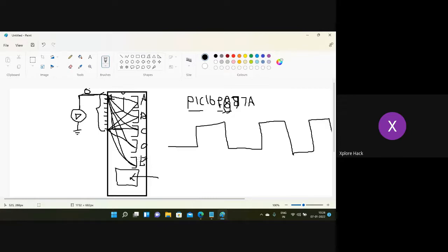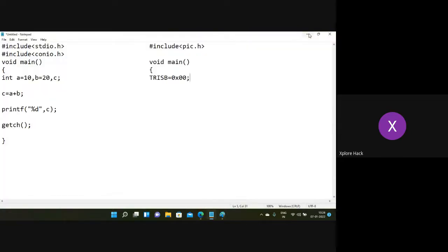This microcontroller can take 8 pins in each port, and if you are configuring the pins as output, then you have to give 0 in this place. After this, we cannot add anything within this. Instead, we can activate the pins and ports here. If you want to activate a specific pin, you can use the number 1 to activate a specific pin. Okay, as you know, here we are using a hexadecimal number based system. With the help of this hexadecimal number system, you can control an individual pin with a given number.